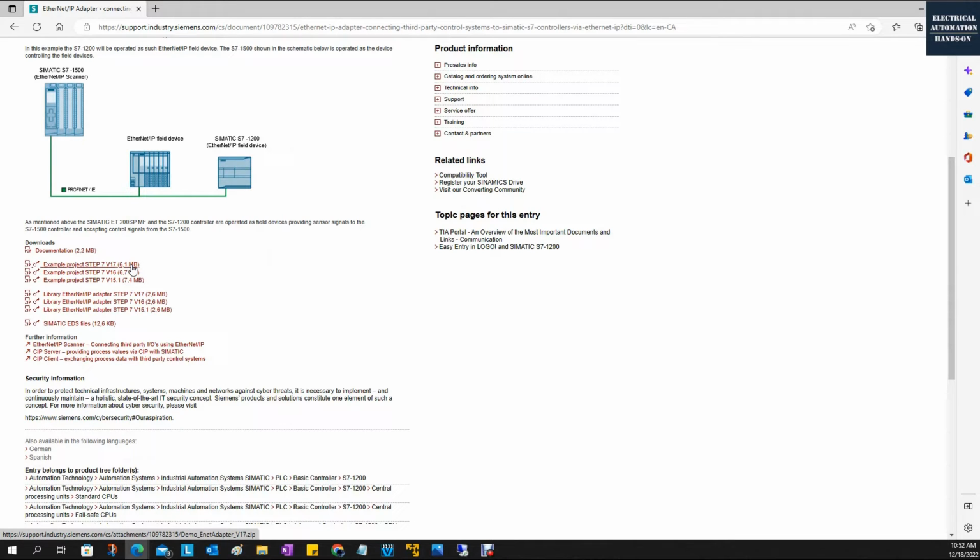Let's firstly implement the device side, because the device side will provide us the instance ID, the assembly number, the input and output ID numbers, and the configuration number. Once we implement the device side, it will be very quick and easy to match the configuration on the YASKAWA side, in the MotionWorks software. Okay, let's download this example program.